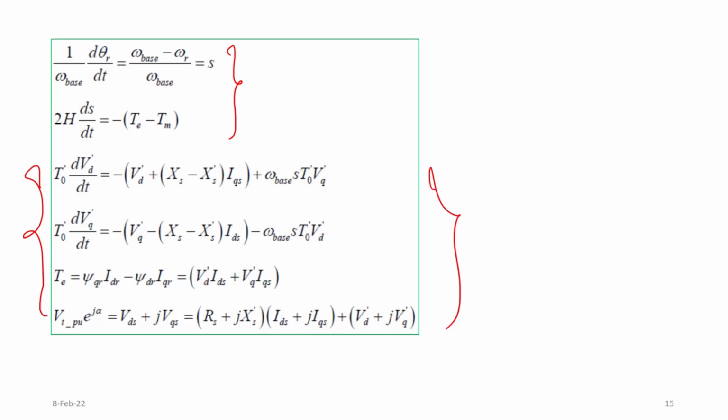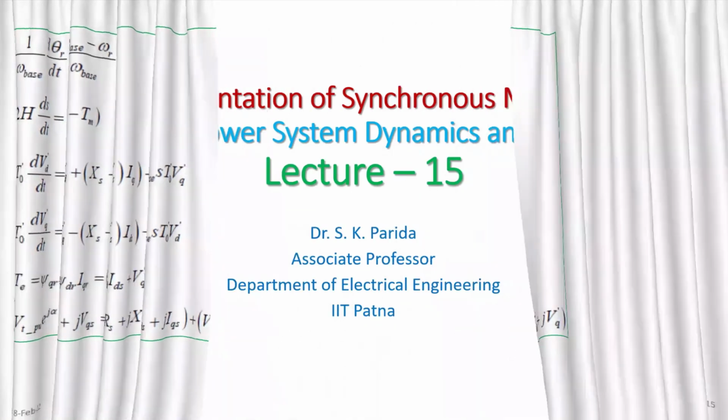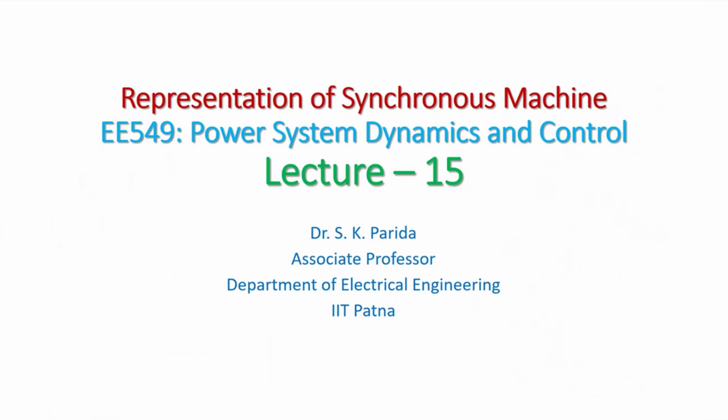So we have seen the load models: the constant impedance model, then the constant current and constant power models. Then we discussed the model that considers the effect of frequency; the frequency term is also added. And in order to incorporate large motoring loads, we have developed the model for a synchronous motor and an induction motor as well. The synchronous motor model is the same as the synchronous generator except for very little change, and the induction motor model we have also seen. So today we have completed the modeling part, and we'll stop here, okay?